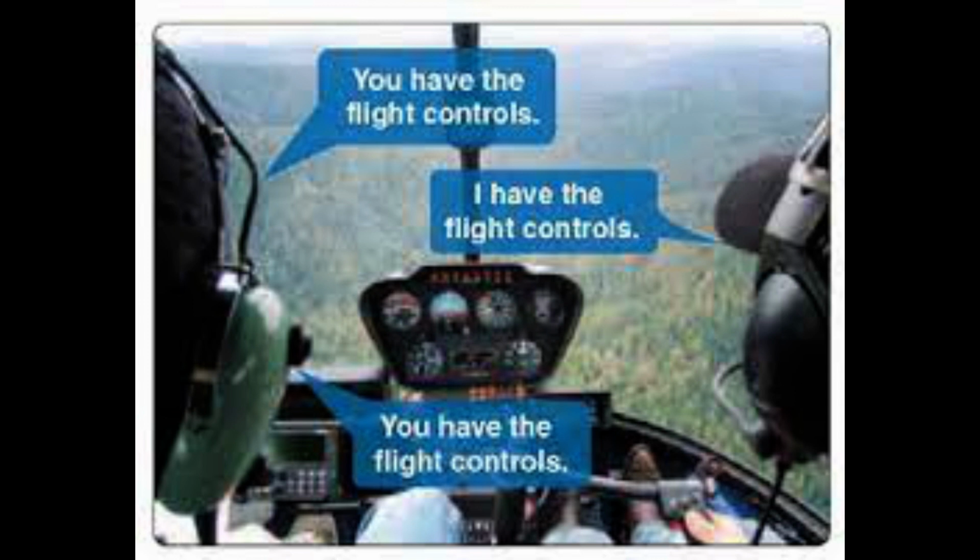Pre-flighting the autopilot. The POH or Aircraft Flight Manual, AFM, supplement for each FD/autopilot system contains a pre-flight check procedure that must be performed before departure. As with other pre-flight inspection items, this check allows you to ensure that the autopilot is operating correctly before depending on it in the air.